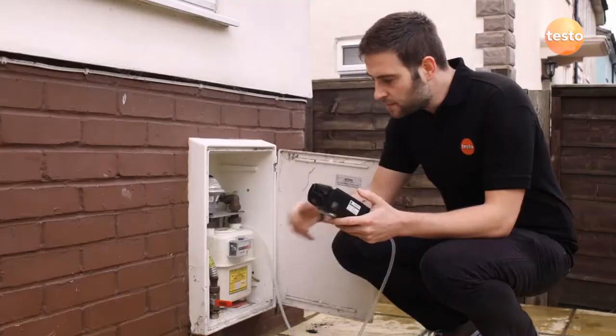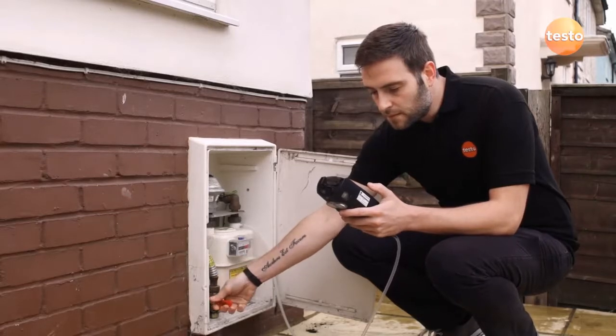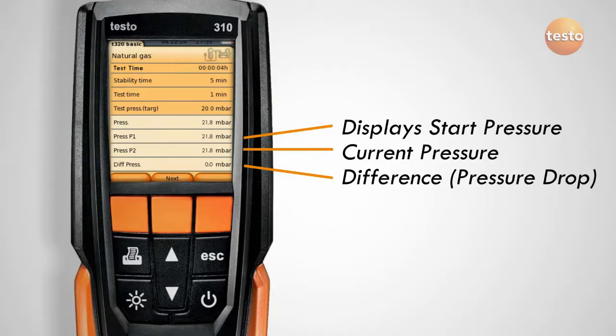Again, open and close the gas valve, and use the blue gas relief valve to set the target pressure, then start the stabilization timer. Ensure the reading is stable before proceeding with the tightness test. Industry standards originated for carrying out the tightness test with the U-gauge and say there should be no discernible pressure drop during the tightness test.